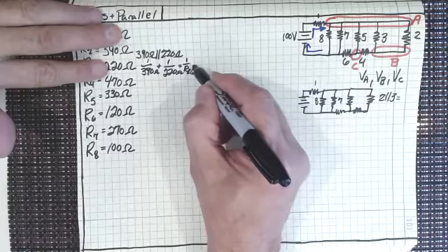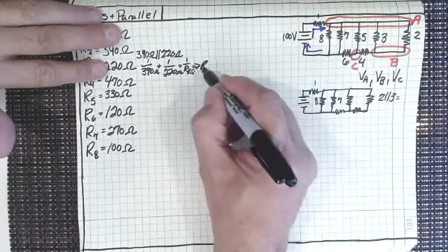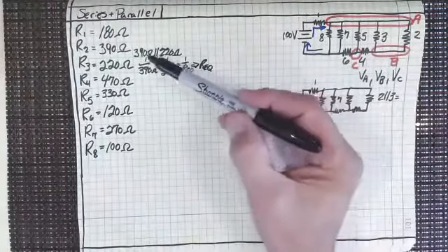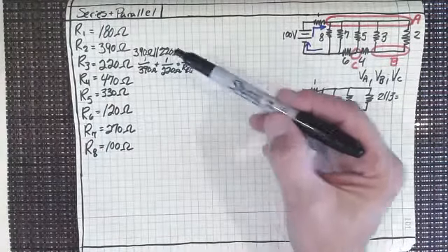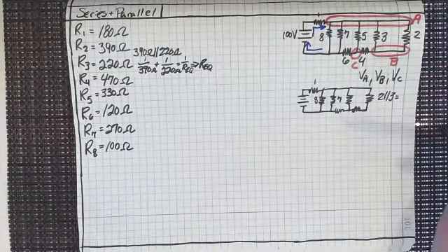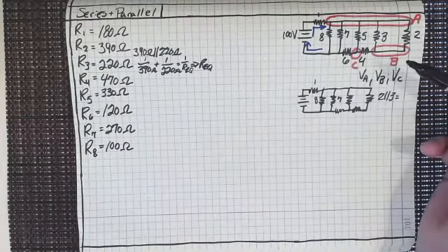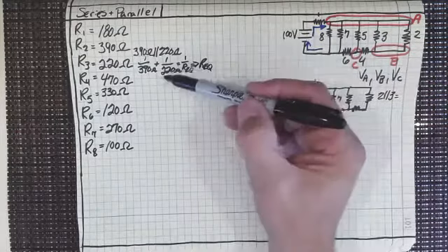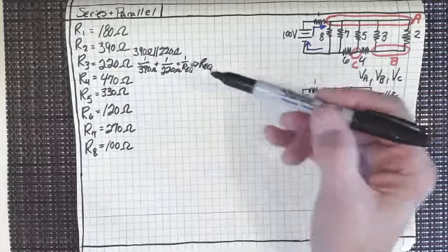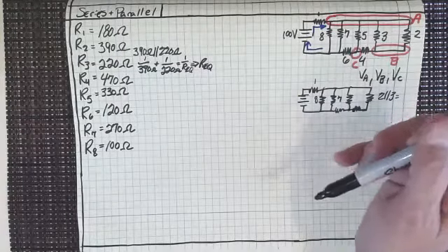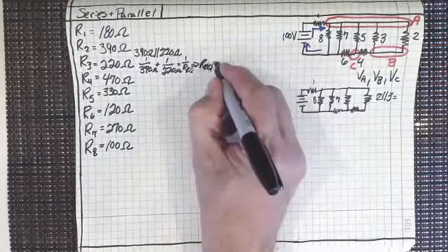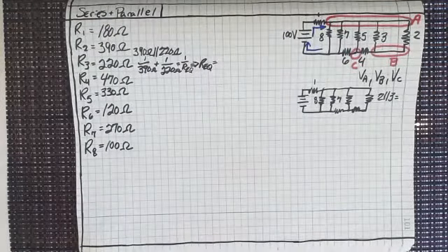So what that tells us is that the equivalent resistance, and of course these two in parallel, the first thing that you want to say is, all right, that's 390, that's 220. So it's got to be less than 220 ohms. If your calculator tells you that REQ is not less than 220 ohms, you know you've made a mistake. That's sort of the acid test. You may have hit the wrong button or something like that, but let's just do it.